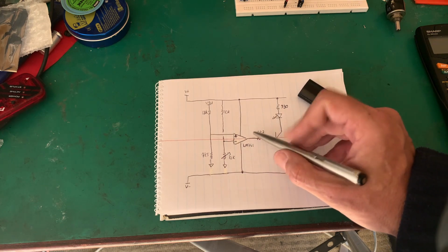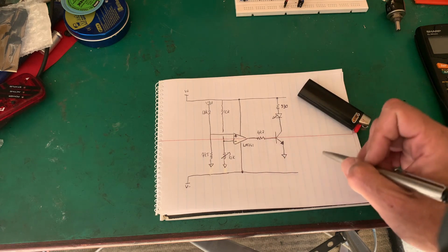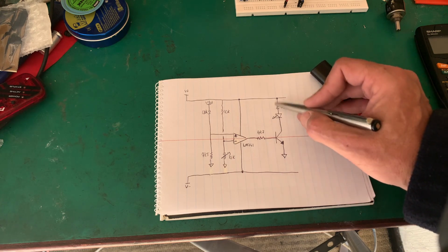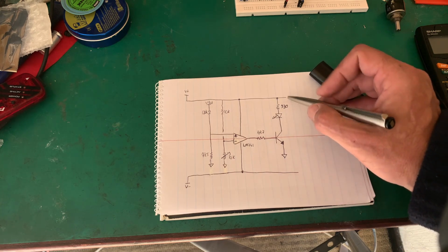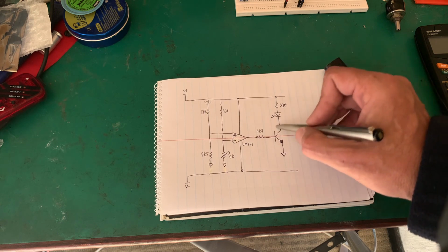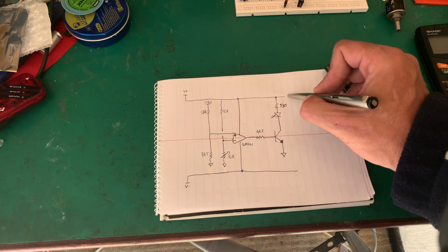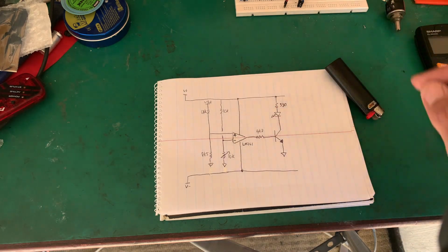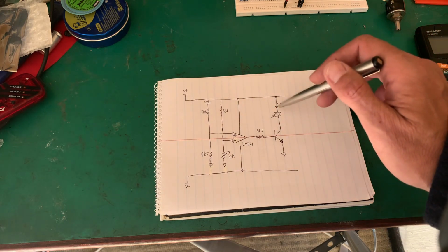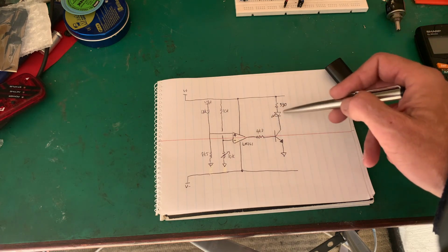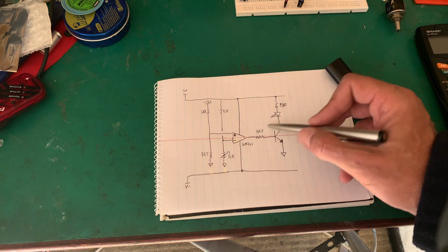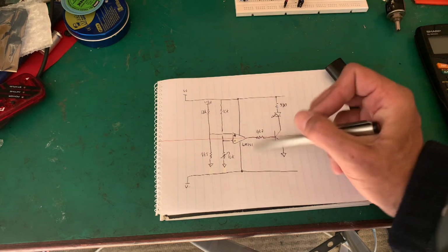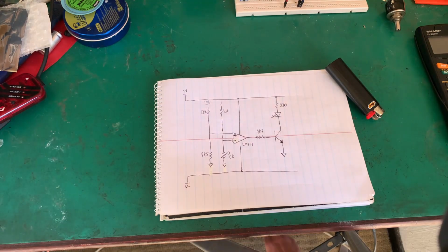And that's simple enough. We need the current limiting resistor on the base to set up our gain. 330 ohm current limiting resistor up there, LED back down to ground, because this is going to be 7.5. It's half of our 15. So we can use op-amps as comparators to drive indication lights. Of course, you could probably drive the LED direct, but why not use a little transistor, 2N3904 or something like that?